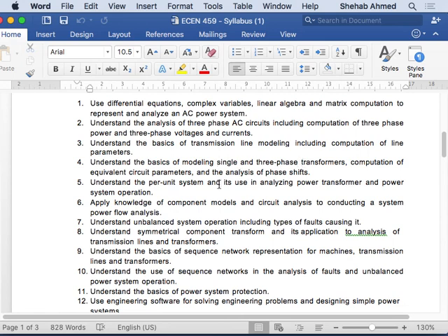And then, okay, you've taken all this stuff and plugged it into the circuit. These devices were all at different voltages and different power levels, etc. How do you make them interact? This will be using a normalization of the system. So you will find a way to normalize the values and ratings of all these components. Because if you're dealing with an 11 kilovolt transformer and a 5 kilovolt transformer and a 20 kilovolt transformer and a 30 kilovolt transformer, you want to put all of those in the same single circuit that I drew, right? How do you do that?